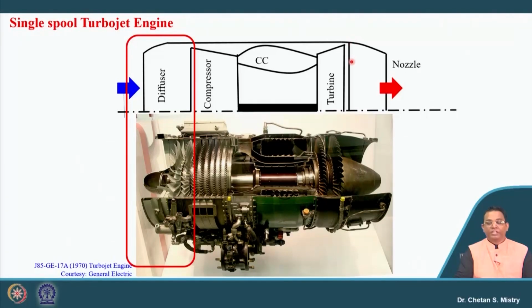This high energy will pass through the nozzle, and if we look at this nozzle, at the entry we have a higher area, and at the exit we have a small area. So we can say this is my converging passage. Now when we say converging passage, that means this is a device which is used for increasing the velocity, and that's what we are looking for. This is what represents the exhaust from my nozzle.